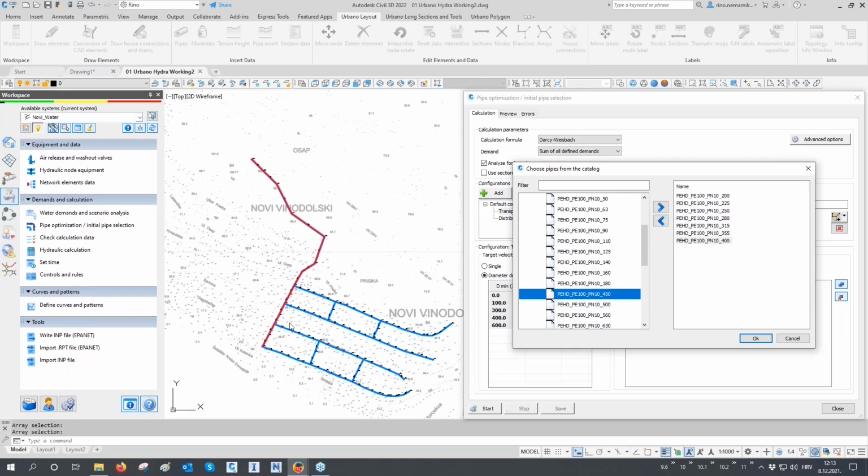I don't know which pipes are optimal here, but based on some logical thinking, by doing this selection, I reduced the time for the software to compute, and immediately at the start I removed some solutions that are basically not solutions because they are really bad solutions. For example, if you take a pipe of 32 millimeters, the software will try to see where this pipe can go, and it will just take time to compute something that is not useful.